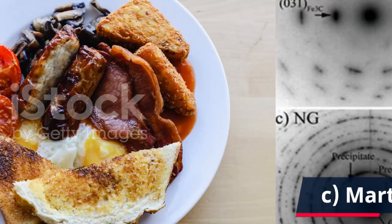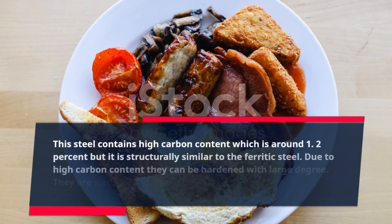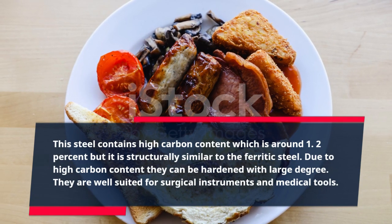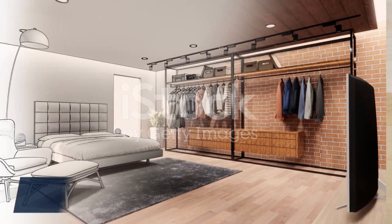C. Martensitic. This steel contains high carbon content which is around 1–2%, but it is structurally similar to the ferritic steel. Due to high carbon content they can be hardened with large degree. They are well suited for surgical instruments and medical tools.